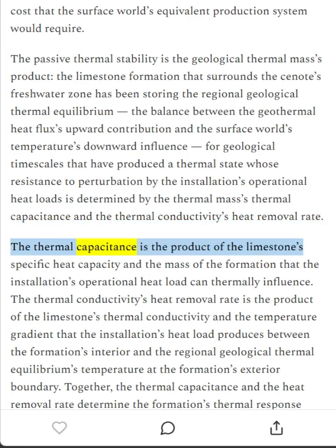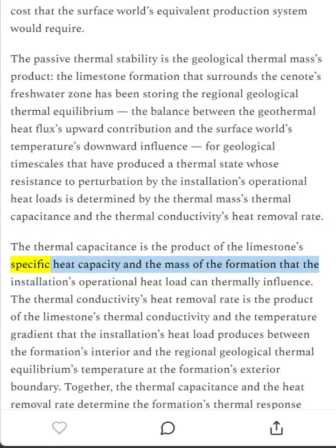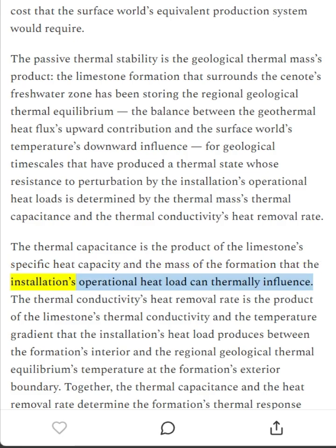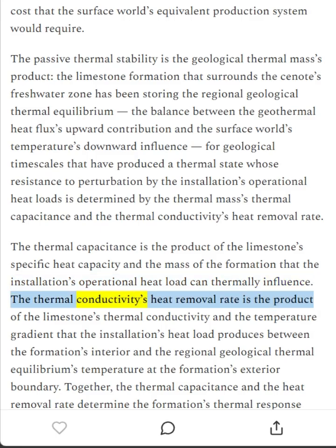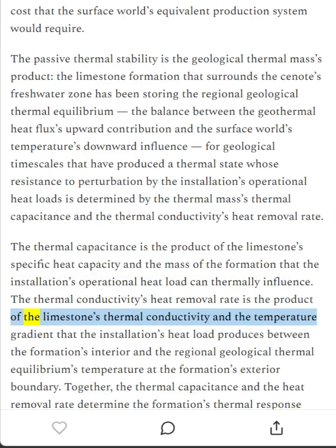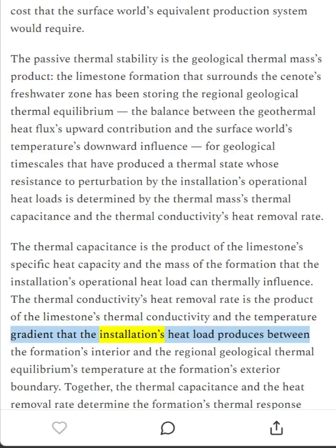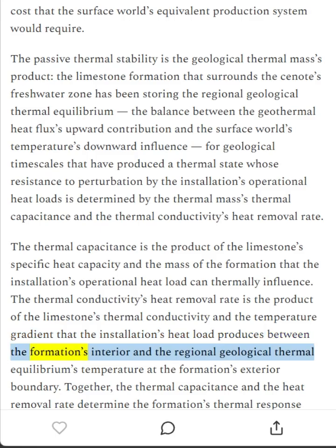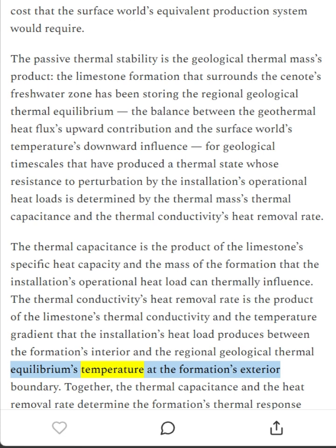The thermal capacitance is the product of the limestone's specific heat capacity and the mass of the formation that the installation's operational heat load can thermally influence. The thermal conductivity's heat removal rate is the product of the limestone's thermal conductivity and the temperature gradient that the installation's heat load produces between the formation's interior and the regional geological thermal equilibrium's temperature at the formation's exterior boundary.